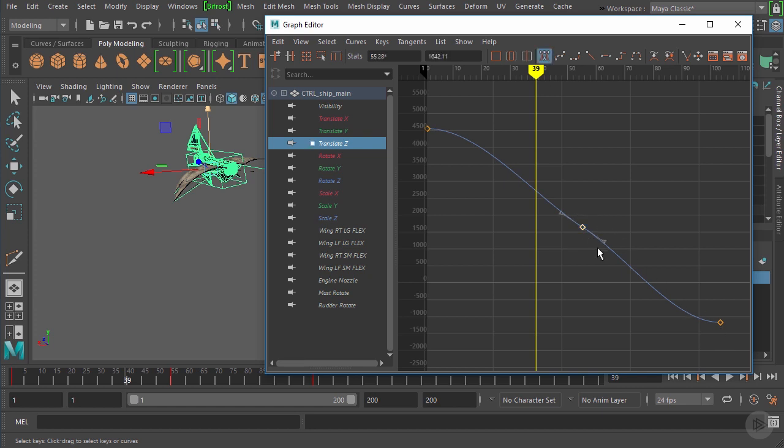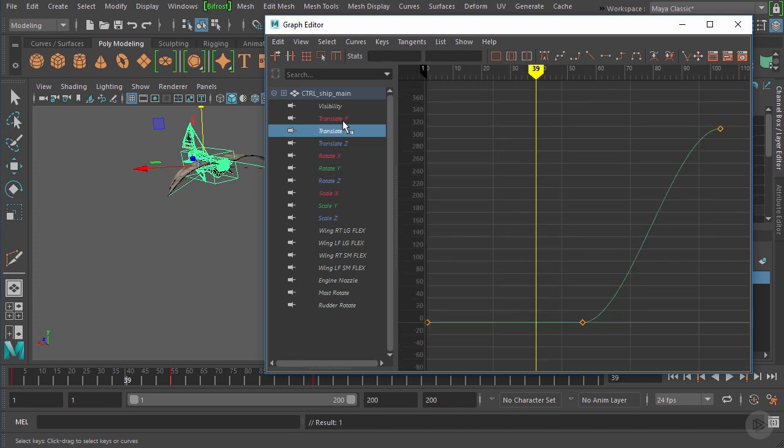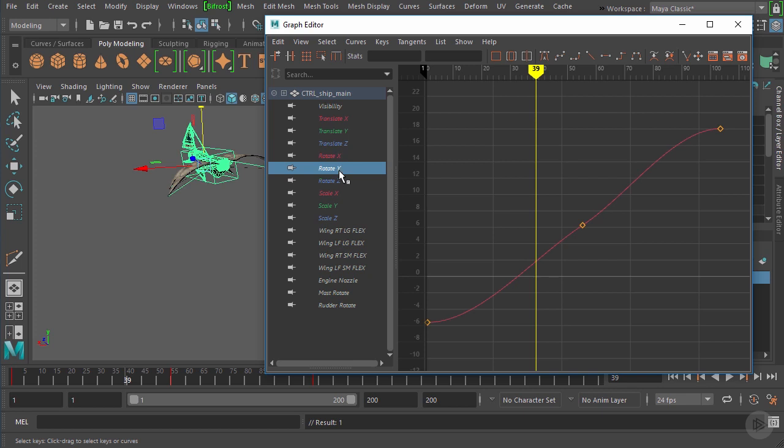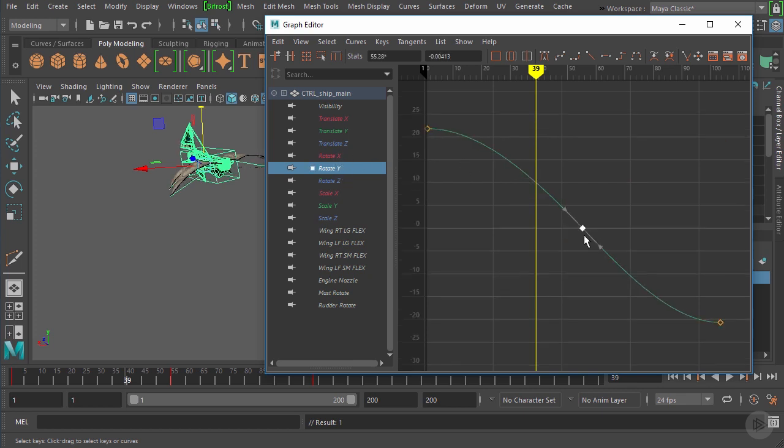If we select a particular keyframe, we can change the tangent handles to make it smoother or flatten it out. Here, the model would move, slow down its movement, and then speed it back up again. This is more of a smooth transition. So you can go in and actually modify how that interpolation happens, whether you want it to be a completely linear interpolation or like this, very smooth spline-based interpolation.